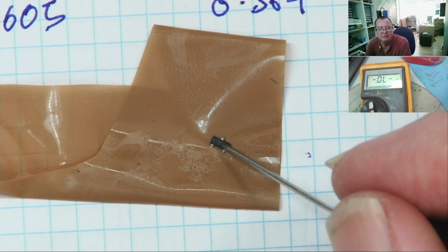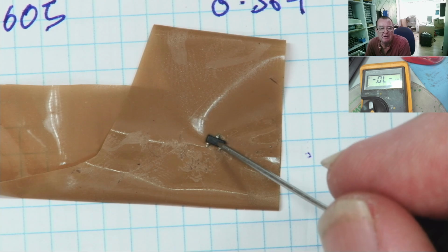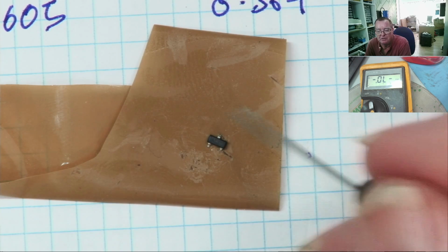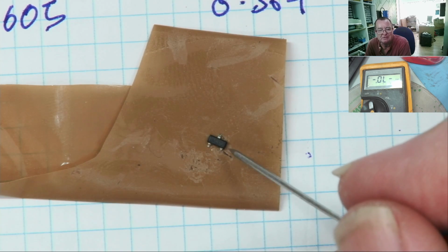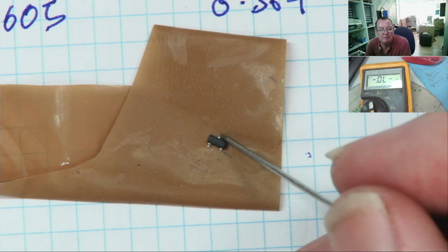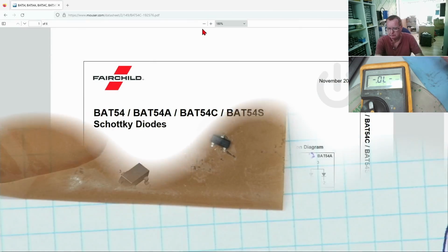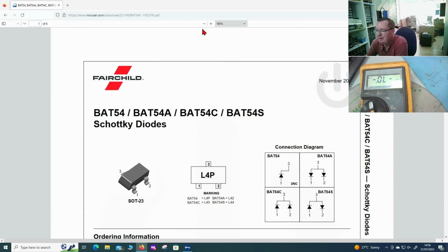Of course they probably do, just to confuse matters even further, but I'll show you why you're going to find things that look like this, transistors, that read where the base is here. And the reason is because of these things. So these are diode matrices. You can see the package is exactly the same. SOT23, small outline transistor, 2.3, which is 2mm by 3mm. That's why it's called that.